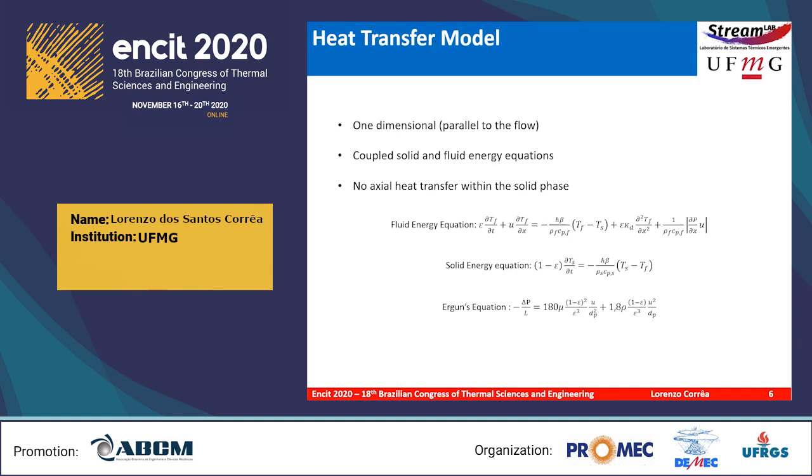As the axial heat transfer wasn't considered in the solid phase, the solid energy equation presents that the change in energy in a solid volume is only related to the convection with the fluid for that volume. And the last equation here is Ergun's equation for the viscous friction in a porous media.